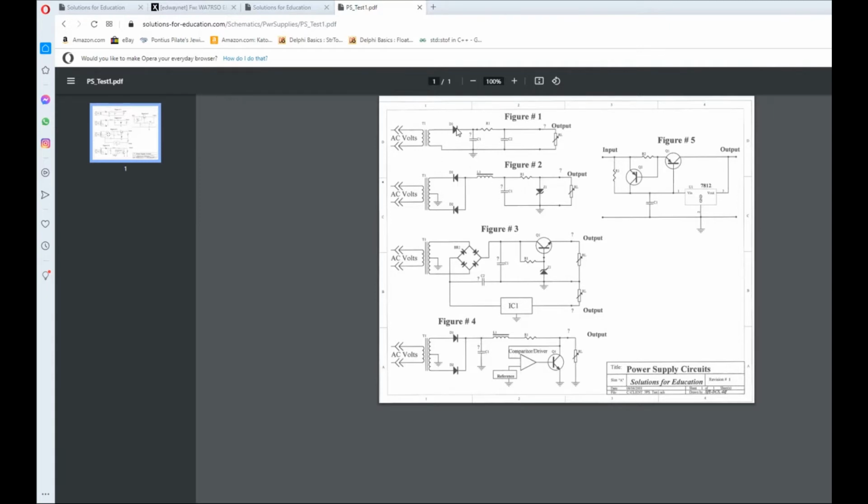Okay, this is a half wave because there's only half of the time that the rectifier is working. However, the voltages here get up accordingly. Now, down here you have what's called a full wave center tap. And the full wave center tap then gives you your peaks twice per cycle. And so therefore, it's easier to rectify it and to filter it out.